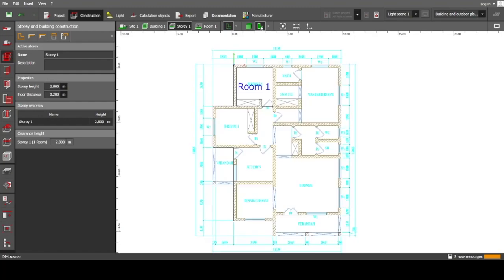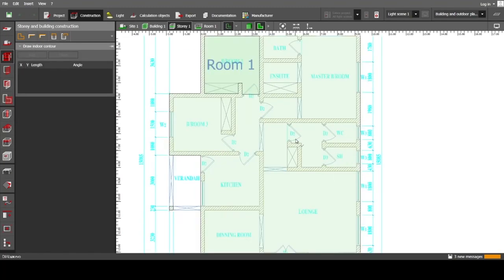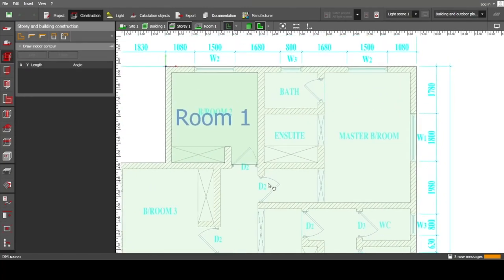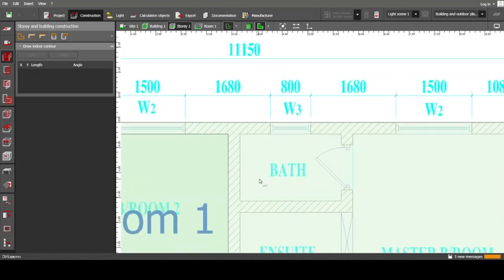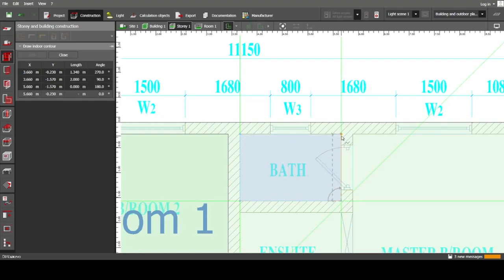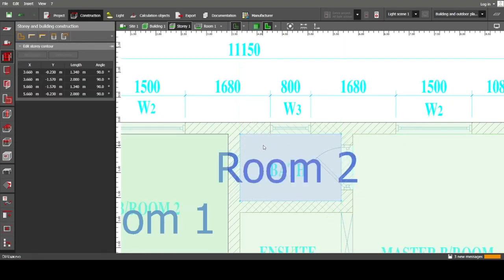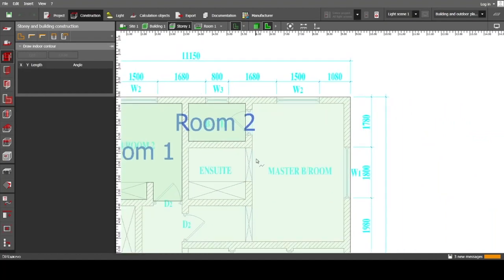No problem. I'll demonstrate one more time how to set room division inside your house. First, click this tool over here, and then click on one corner of the room that you wish to set the division. After that, you can work your way over every corner of the room until you are back to the first point that you made. And just click like this, and that's it!